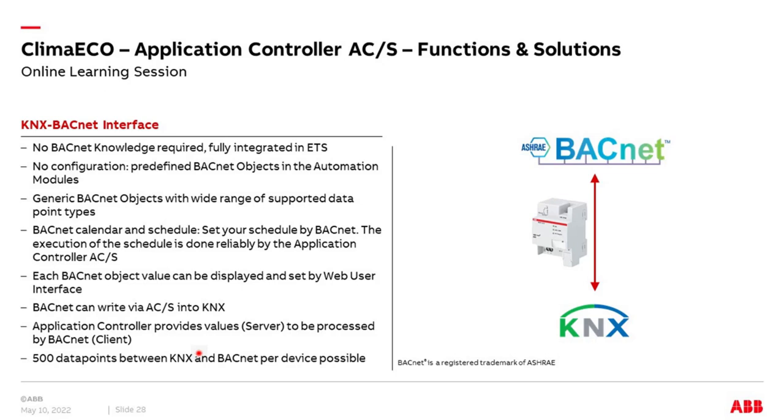Of course, it's not forbidden to use a second one. Keep in mind, this is not a pure BACnet KNX gateway, the application controller. It's an additional function we have, beside all the others. But it's a full BACnet gateway to KNX with up to 500 data points.